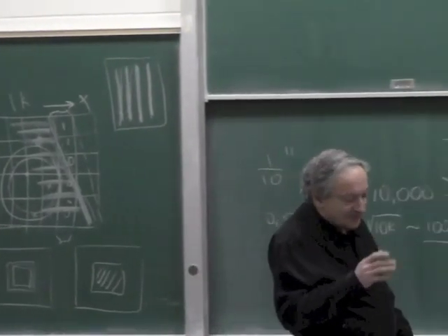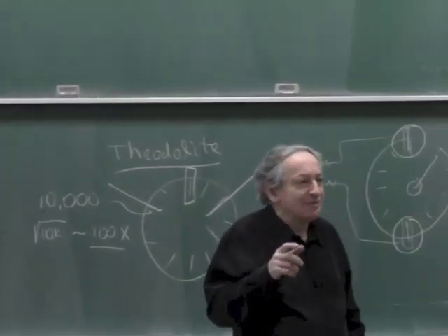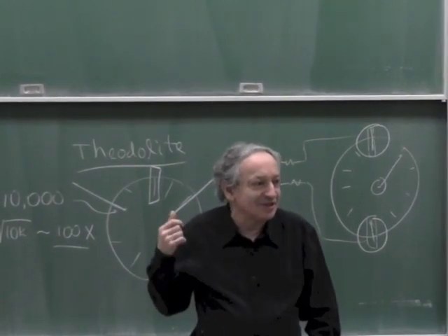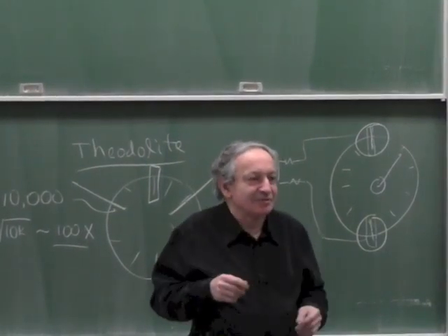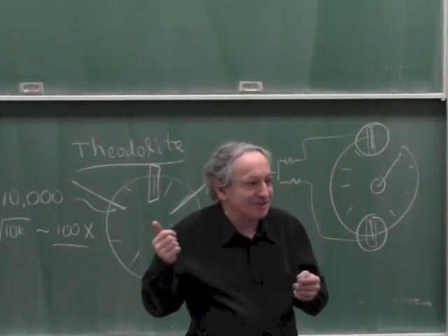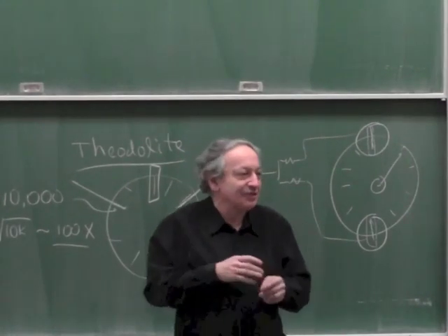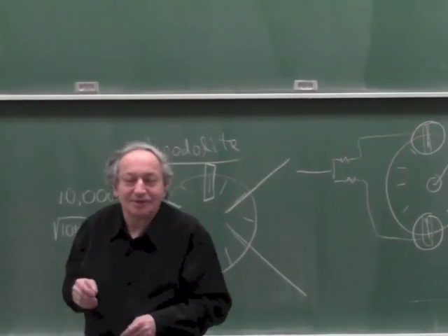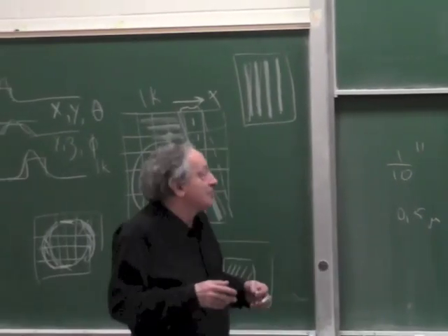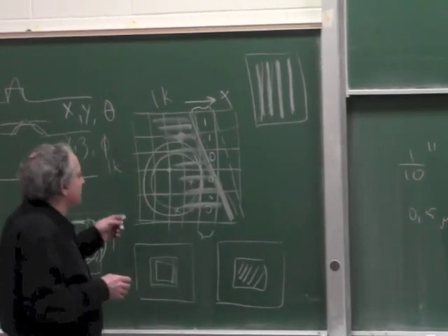Okay? There's actually some student here in MECH who did a project where you can do it with one camera, because the camera is color and you don't really need color. So you can illuminate a target with red and blue and green LEDs and look at each image separately. So you have like 3 cameras in one. So if you're clever enough, you can do it in one camera. If not, you do 2 cameras. So it's a very, very versatile device, because first you can measure 6 degrees of freedom if you want to, and there is other ways to measure 6 degrees of freedom.